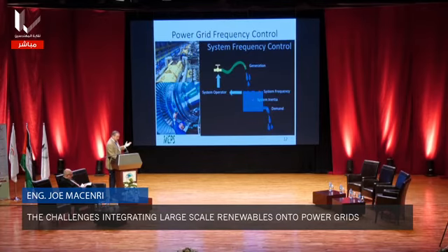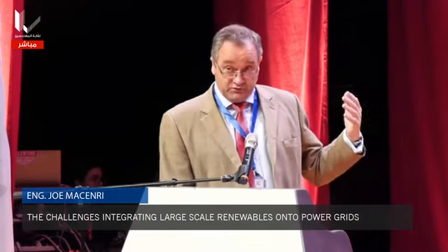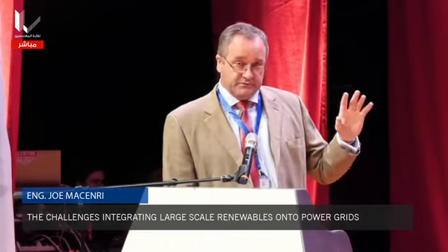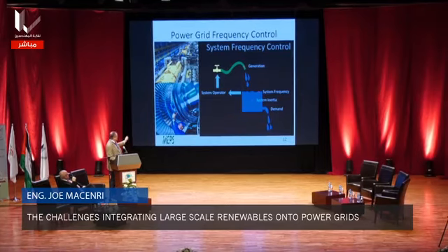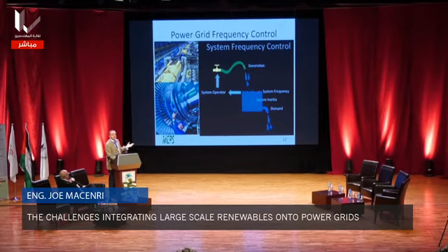Okay, in a traditional power system, which power system engineers have known for about 100 years, you essentially had a grid and you have a number, not a particularly large number, but a medium number of large turbines connected to it. These are generally high-speed turbines. You can see somebody working on one here, the size of them. So these are spinning at high speed. What that means is you have a lot of mechanical energy, kinetic energy in the system in those large turbines.